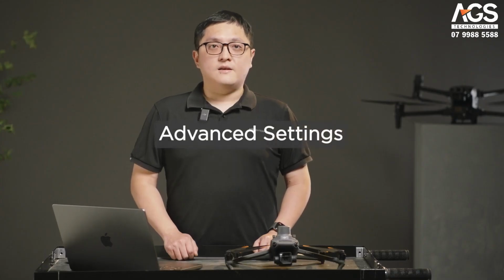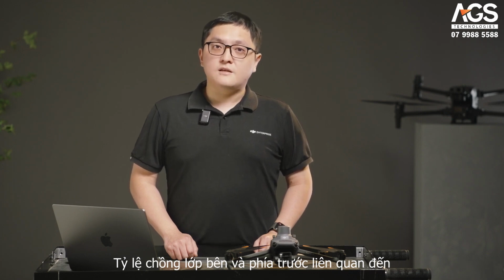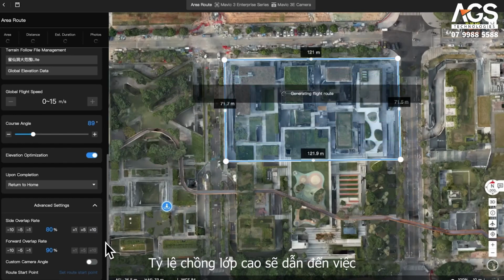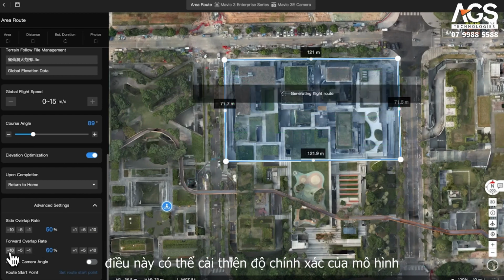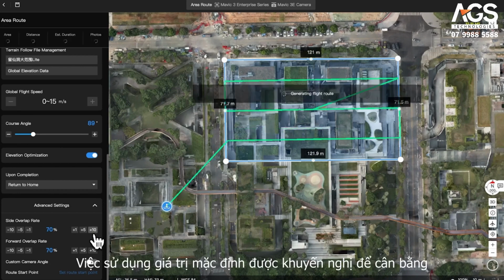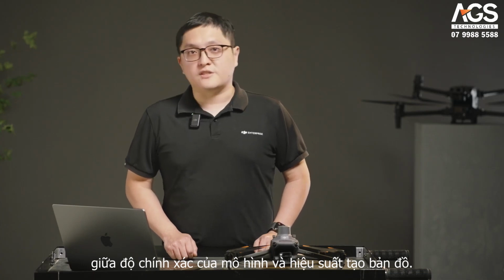Advanced settings. Side and frontal overlap ratios refer to the density of photography during the mission. A higher overlap ratio results in more photos taken over the same distance, which can improve the model accuracy but slow down the flight speed. Using the default values is recommended for a balance between model accuracy and mapping efficiency.